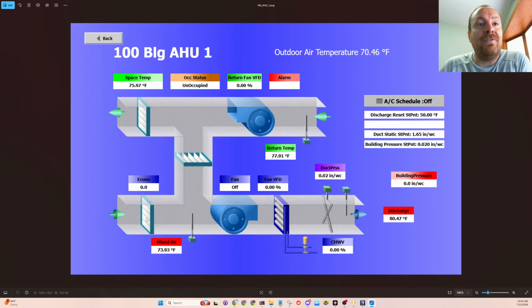And there is a fault that we looked at today where there's a mismatch between the outside air temperature and the mixing air temperature. I think that's related to the outside air temperature reading about 5 degrees higher than what you get from the web. So it's my own little theory. We don't have a lot of information to say that, but it is what it is.